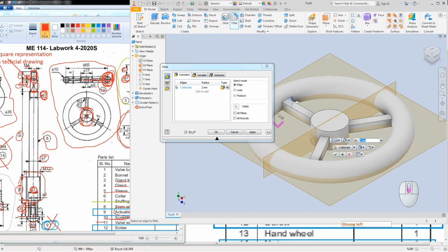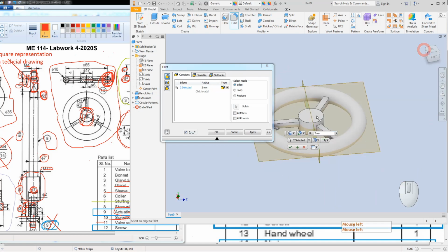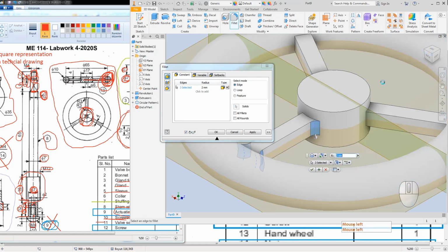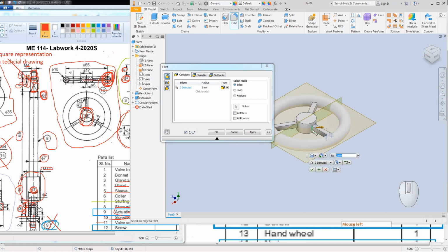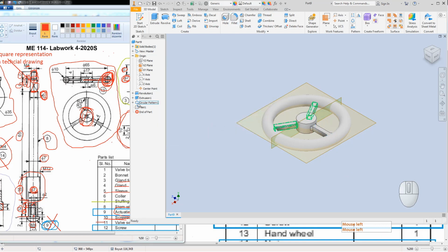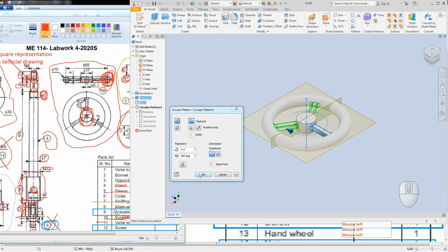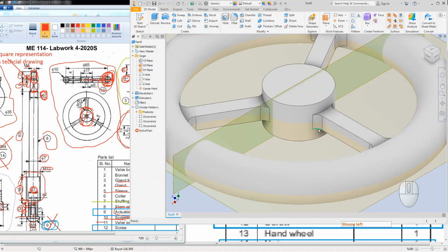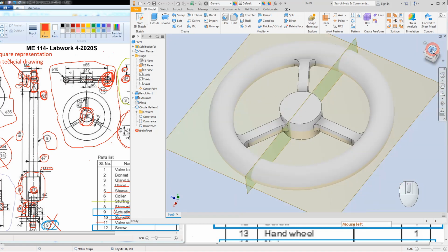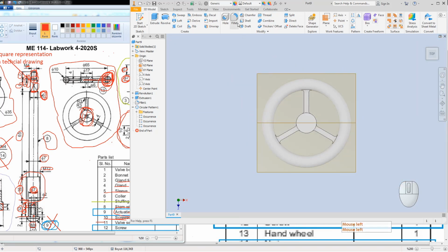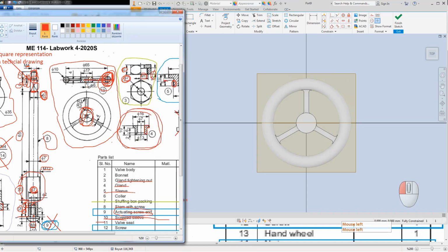On the other side, this is also on this side. Also this one. We move this fillet and also copy this fillet properties to these, and have the copies with the fillet features. Also, I'm going to use the top side again to see better. Start a new sketch on XY plane, where I have the 6 millimeter square extrusion here.